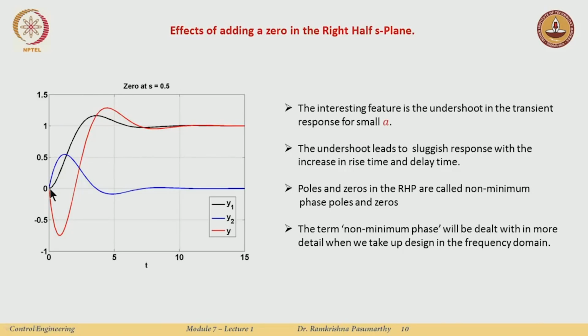But initially, when I switch this on, I am actually going away from the target, which might make me want to stop, because the system is doing something very weird. But if I let it go for a little while, it reaches a minimum here, and then starts going up, and then does something similar to the previous case: there is increased overshoot. The response is a little slower, the overshoot has increased, and the settling time does not change much.